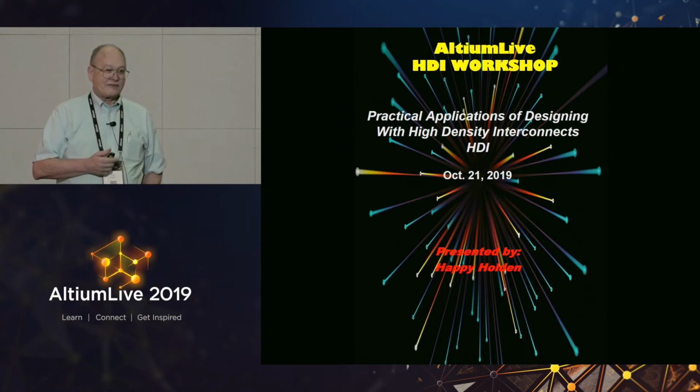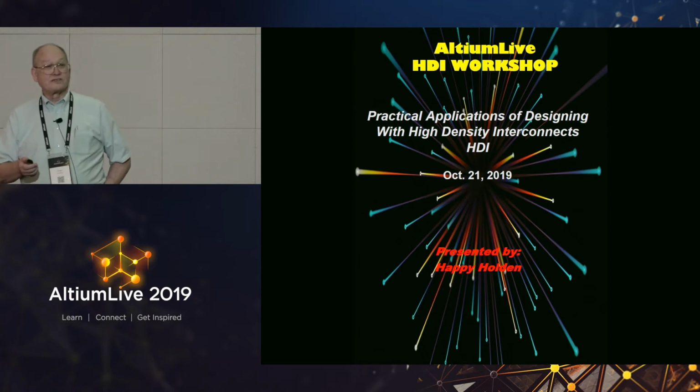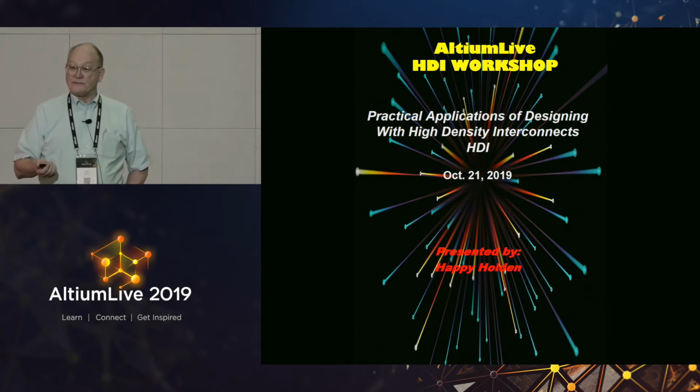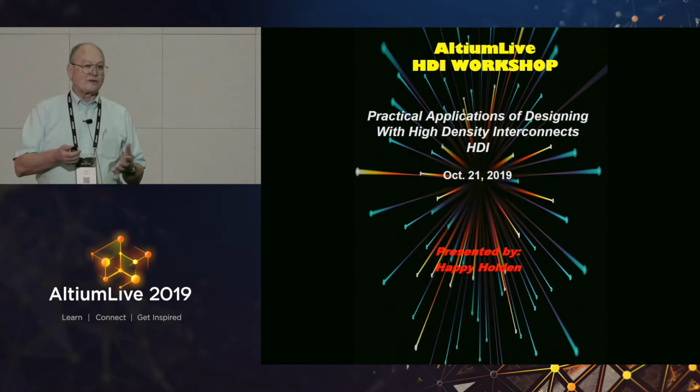Well, for people like myself that work a lot with the semiconductor industry, since the semiconductor industry is at 7 nanometers, the famous phrase will be, if you're not using HDI today, you will be very soon. And the reason is that the rise time of modern integrated circuits requires that everything be a transmission line. And the pitch is shrinking as they increase the number of gates. And with that shorter rise and fall time, they have to have more grounding pins.